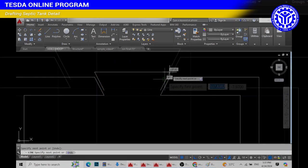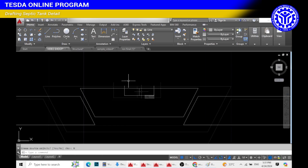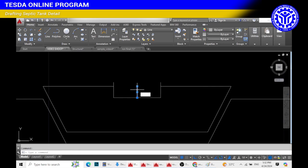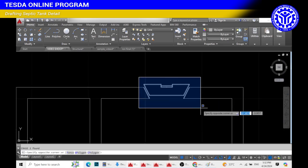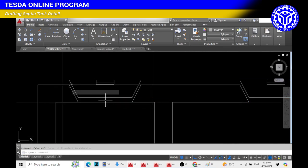Connect the diagonal lines using the Line command. Using the Line command, specify the indent on the manhole cover. Copy the manhole cover and opening to the smaller chamber using the CO command.